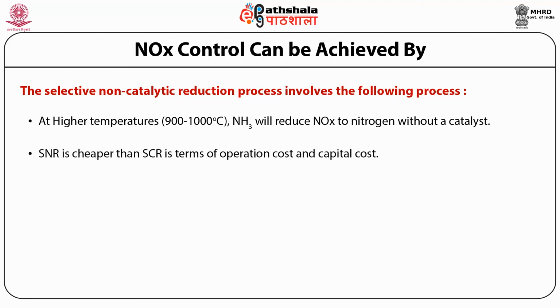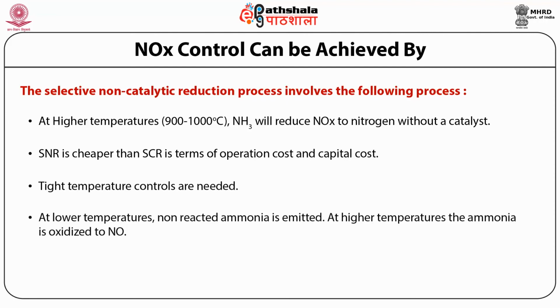SNCR is cheaper than SCR in terms of operation cost and capital cost. Tight temperature controls are needed. At lower temperature, non-reacted ammonia is emitted. At high temperature, the ammonia is oxidized to nitrous oxide.